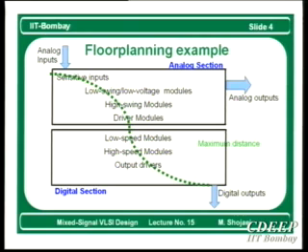In fact, a digital output, which is coming from a digital driver, is the worst output with respect to switching noise and any other source of noise which is coming from the circuit operation. And analog input is the most sensitive. So this is the first rule of thumb. The second rule of thumb actually is in the way you observe these modules. You put low swing close to sensitive inputs, low swing modules. Then you go with high swing modules and then drivers.